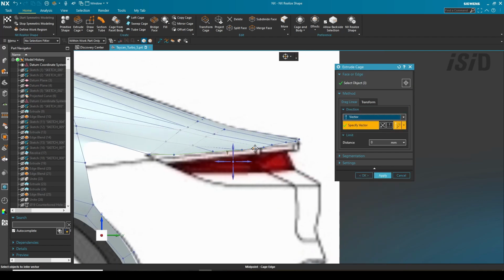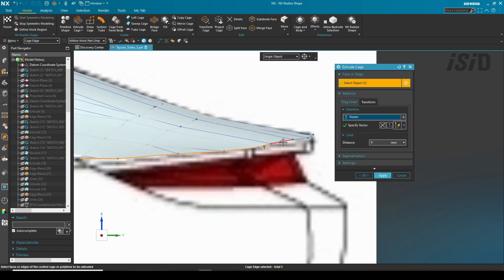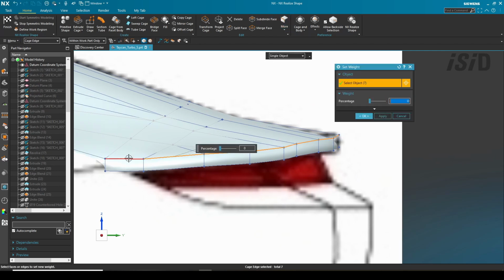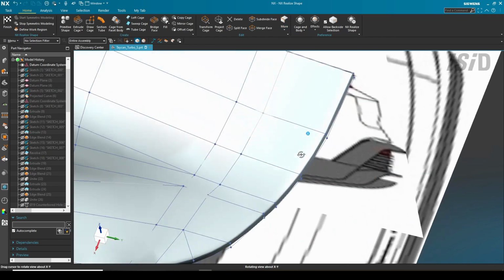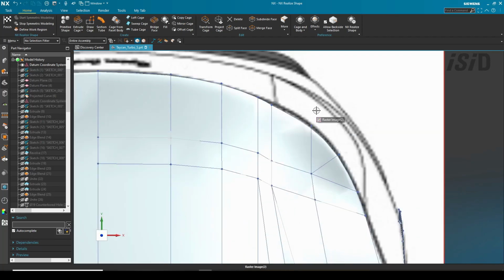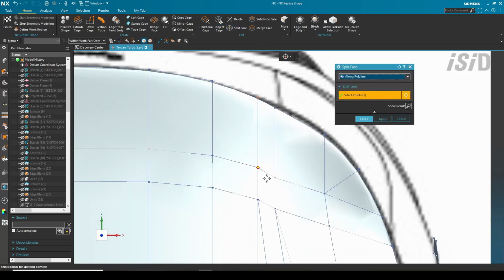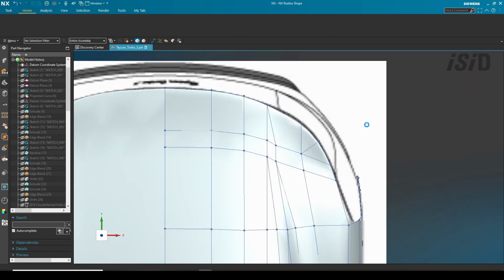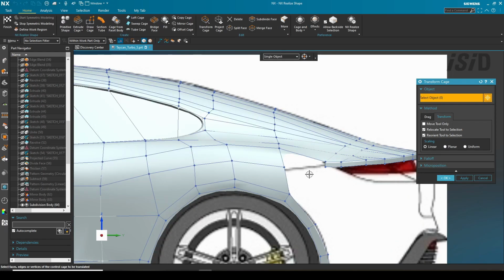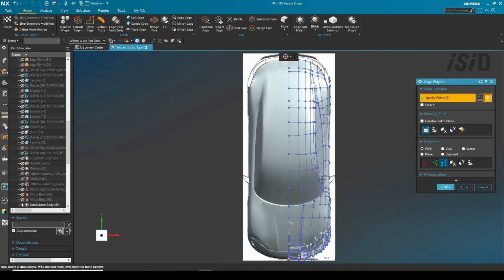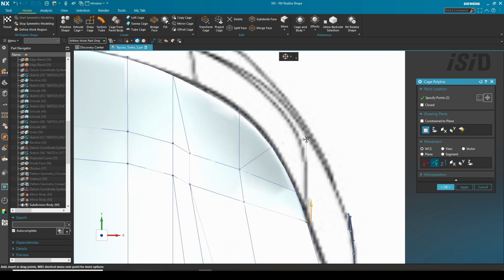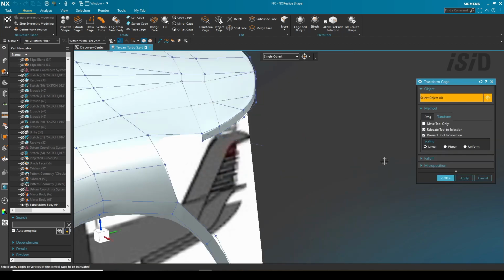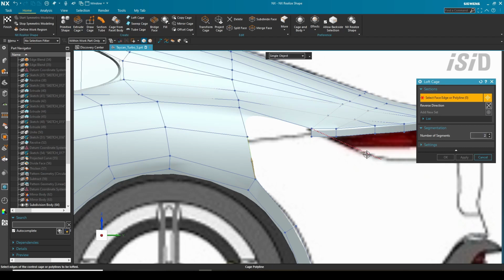And again, I'm ready to add more surface, some refinement to the cage edge using set weight command, and adjust some vertices, maybe merge some faces together or split some faces until I get the desired result.